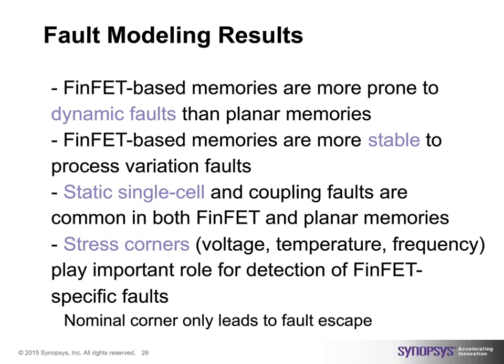Of course, there was also the category where certain planar-oriented faults would not happen or did not happen in the case of FinFET technology. What we observed, though, looking at the bigger picture, is that dynamic faults are more prominent in the FinFET case. That is, not static faults where you would immediately find out the results, but you need multiplicity of reads, multiplicity of writes, so a loop of operations is necessary in the case of FinFET.